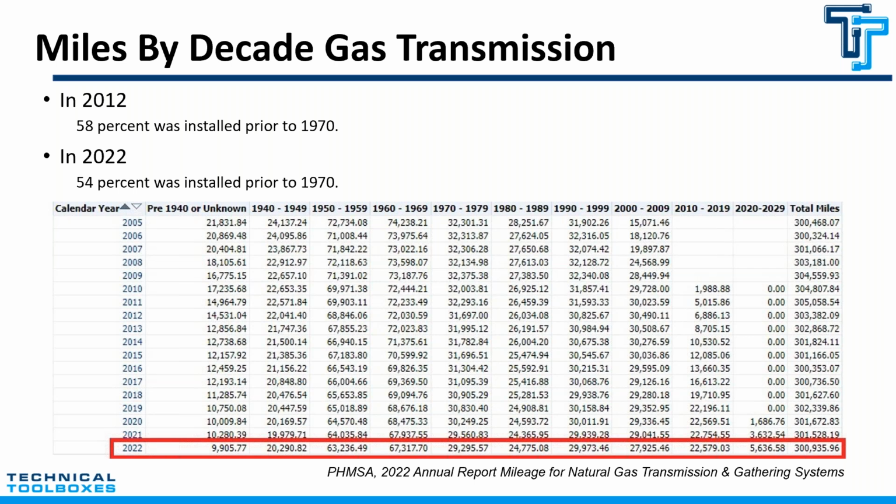So even though there are significant improvements in the replacement that's happening, you are still in a place where hydrotest is an important aspect in your safety process, and it's not going away. If there is one takeaway from this slide, it's the emphasis of how important hydrotest is and why it's still going to be an integral part of your integrity specification and integrity process.